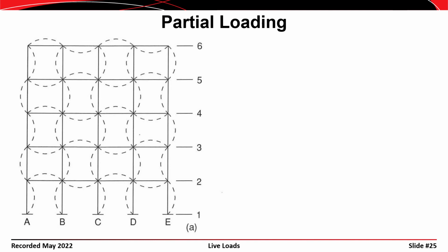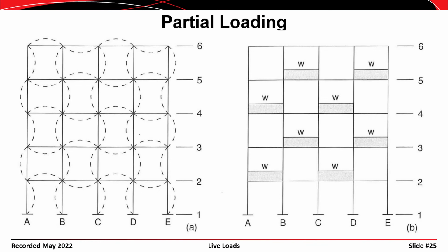In the design of a concrete structure where everything is framed continuous, in other words, there is a moment connection between each beam and each column, then we have to be cognizant of the way the building carries the load when we apply the live load. So consider this. This would be an influence line for positive moment in the middle of one of these bays. If we were going to apply the live load to this structure such as to maximize the positive moment, then we would only load every other bay in a pattern that looks like this.